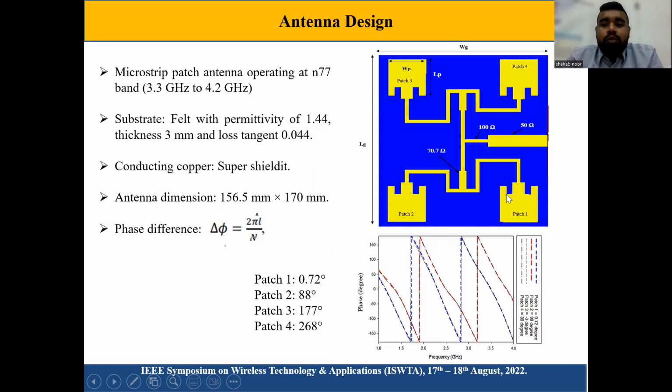We designed based on this formula, and when we simulated it, we observed that the phase of patch 1 is 0.72 degrees, patch 2 is 88, patch 3 is 177, and patch 4 is 268. So it can be seen it is close to 90 degrees.